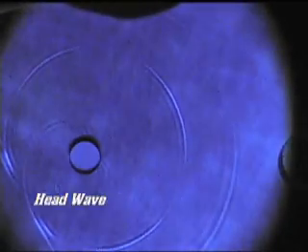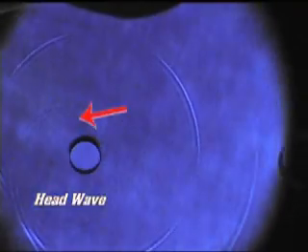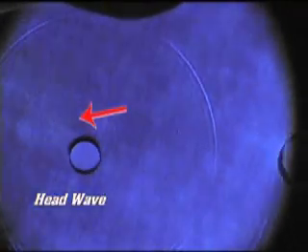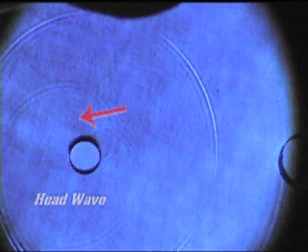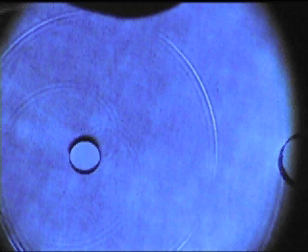The Rayleigh wave is seen linked to the interaction of the shear mode with the free boundary. The linked wavefront can be considered a form of head wave, and it has the appearance of a spiral. This head wave can be seen to account for the post-cursor signals that an ultrasonic technician sees as repetitions on the A-scan, as a result of several circuits around the cylinder.